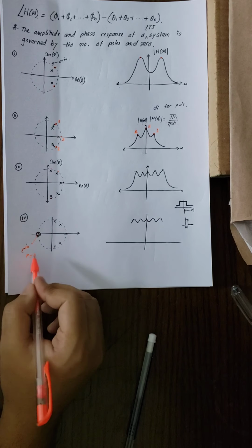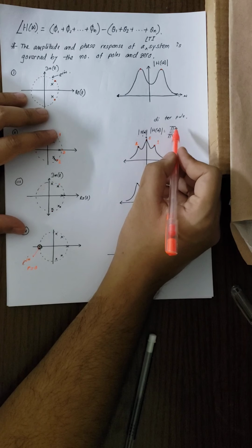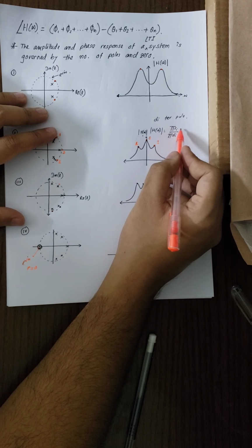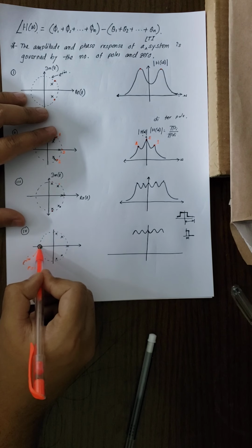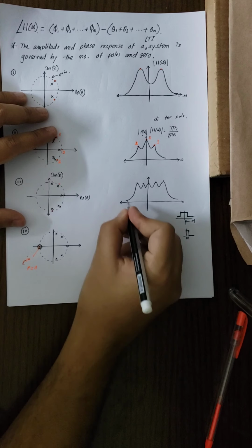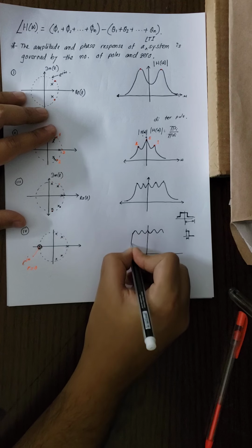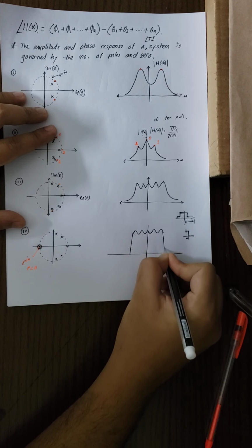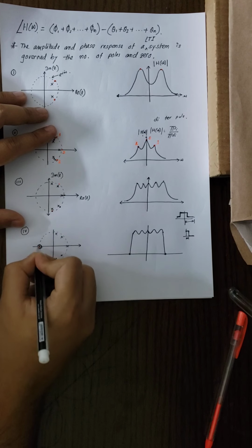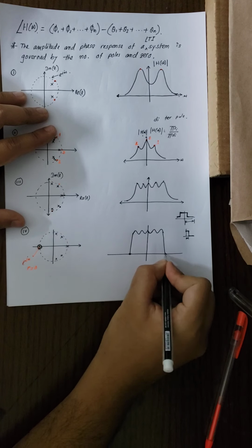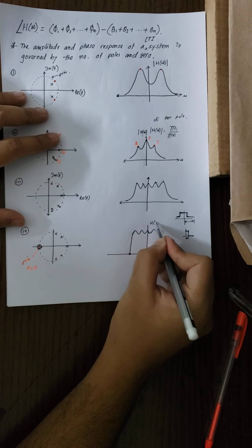So the distance being 0 will give our numerator, shown over here, to be equal to 0, and consequently H of omega at this point will become 0. So simply this was not reaching 0. If we place a zero over here, this will simply reach 0, and these 2 points are identical. If we go clockwise or anti-clockwise, these will be the 2 points. So this is our H of omega.